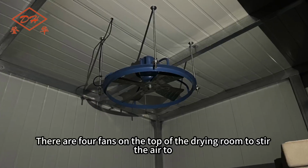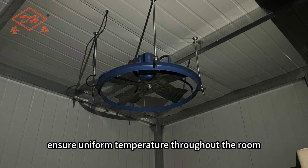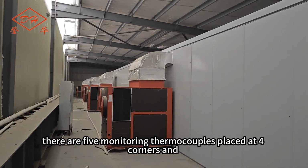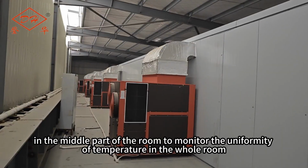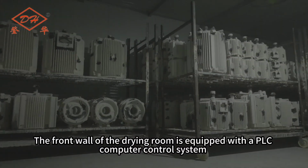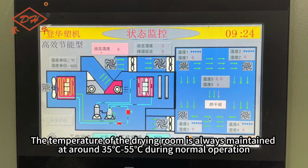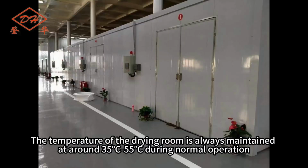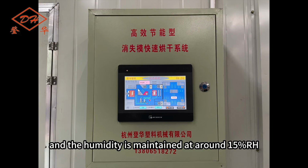There are 4 fans on the top of the drying room to stir the air to ensure uniform temperature throughout the room. In addition, there are 5 monitoring thermocouples placed at 4 corners and in the middle part of the room to monitor the uniformity of temperature in the whole room. The front wall of the drying room is equipped with a PLC computer control system to monitor the drying status of the drying room. The temperature of the drying room is always maintained at around 35 degrees Celsius to 55 degrees Celsius during normal operation, and the humidity is maintained at around 15% RH.